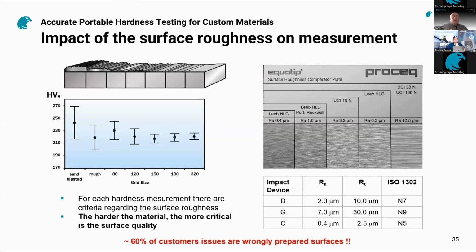The second way that you can tell whether your surface roughness is sufficient is indicated after you've tested. You're averaging a number of readings to obtain a measurement. If you take the recommended 5 measurements, you can generate a statistical significance on that data.